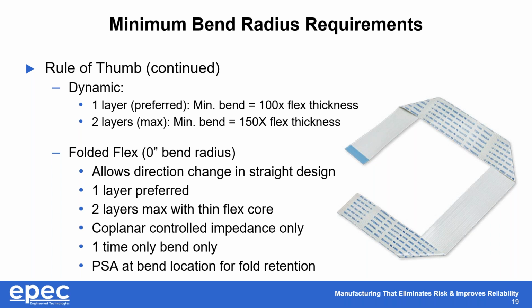If you go beyond 2 layers, it becomes extremely limited. Your minimum bend radius now becomes 150 times your flex thickness.